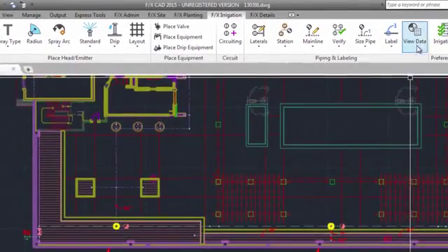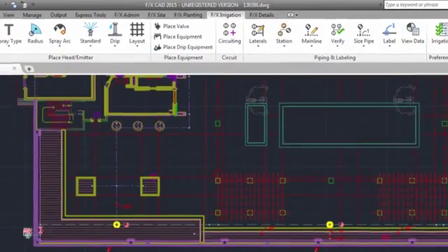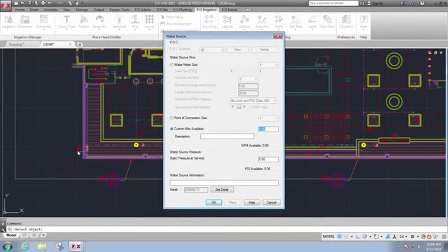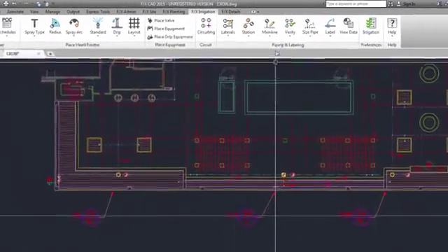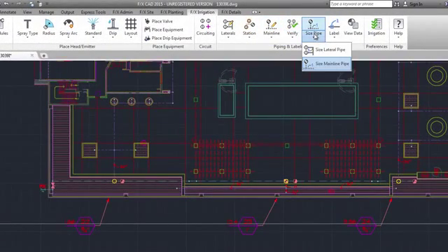Using the View Data button once again, plug this information into the fields for custom pressure and flow. In this case, I need 13 GPM and 57 PSI to ensure the second story design functions properly. Now when I size the mainline, there won't be any errors and the system seems to function properly.